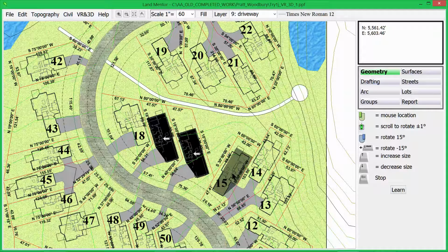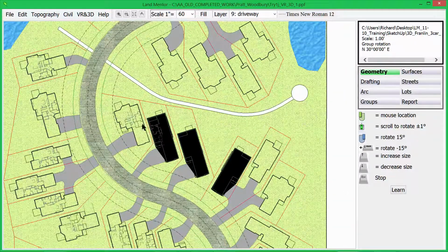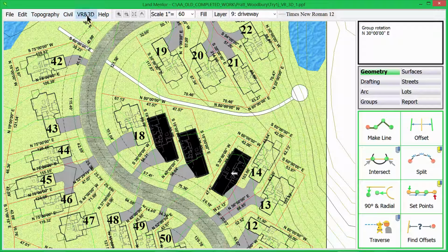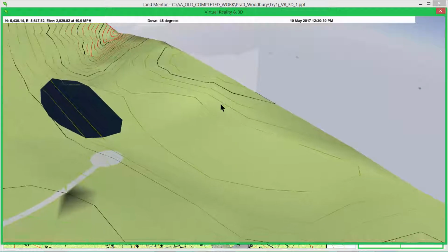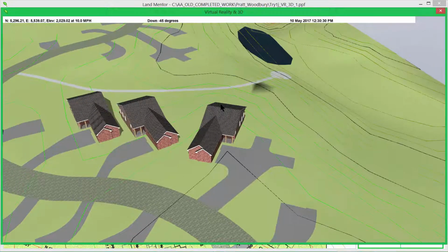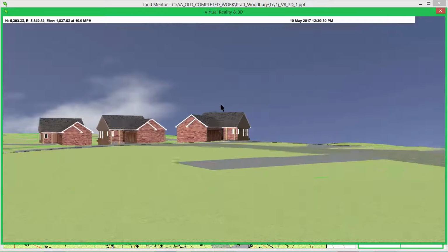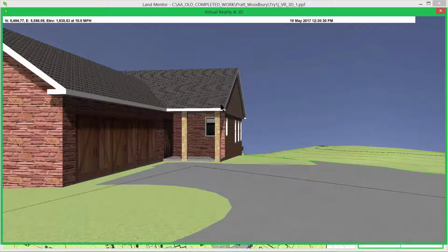And if you have the bearings on the plan, it helps get the angle right, and you'll notice that on the upper right screen as I move this, the angle is shown. And if you leave the lot lines with the bearings on, it's a little bit of a help. So you'll lay them around on your plan and then hit escape, and then you'll view it on occasion to make sure that the units are indeed placed right and they look about right on the plan. And they were changed a little bit as we went along, so that the garage was moved over a little bit, and that's where that difference comes in.